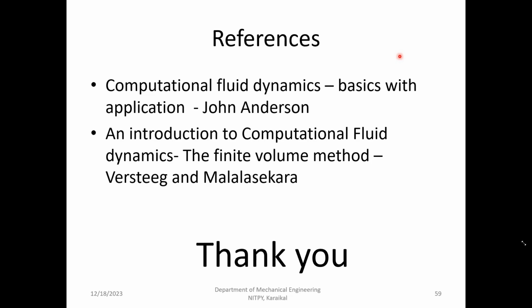That's what the thing is. We are not looking at the residue or the iteration number which the literature says, but you must look at the exit parameters. Maybe temperature at the exit, some parameter if you are going to take, and you have to continue till you get the same value. We can't avoid it. But if your mesh is really better, you'll be getting it in a faster manner. That's the main thing.